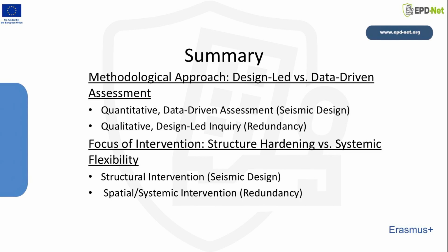The case studies use entirely different methods for deriving solutions and informing strategy, reflecting the nature of the hazard they address: quantitative, data-driven assessment, seismic design. The Faro case study is a rigorous, large-scale application of the vulnerability index-based methodology. This approach quantifies seismic risk as a convolution of hazard, vulnerability, and exposure, and requires detailed, weighted scoring across 14 parameters focused on structural elements, resisting systems, connections, and conservation status.